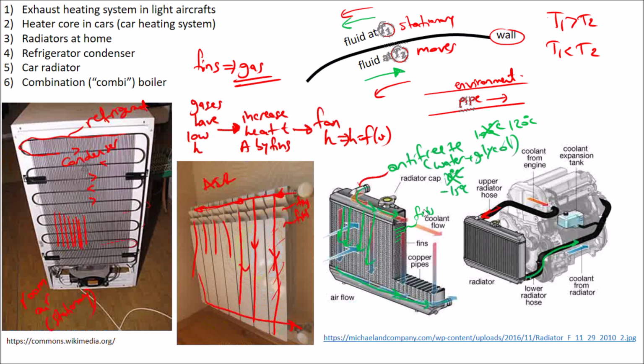So fins again, if we have added fins, it means that we have air or any gas, okay. As we have said, if the fins are not enough for the heat transfer rejection, then we also have a fan here, okay. Then the fan starts to operate, it starts to rotate and helps to increase the value of the h. Also we have other heat exchangers.